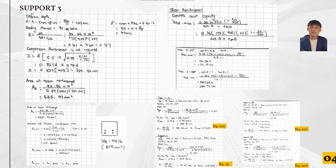And calculate the support 3. For support 3 we have a different effective depth and bending moment, and we calculate the K. As usual we compare with K balance, so the compression reinforcement is not required. We calculate the Z and the area of the tension reinforcement, so we use 4H16 based on the area of the tension reinforcement we calculated, and we use the As provided. Then we calculate the shear reinforcement, which is the compression capacity VRd max, and we substitute it when theta equals 22 and theta equals 45. So we can do all the calculation for span 3 and 3B and the support 3.